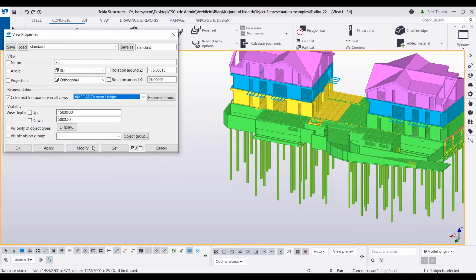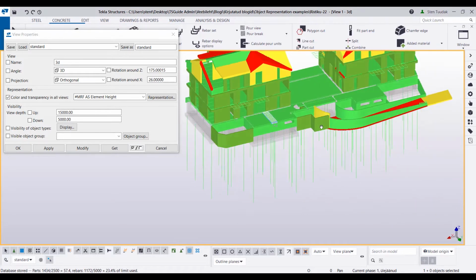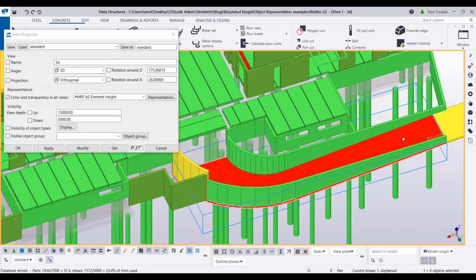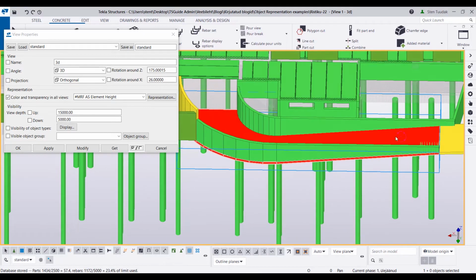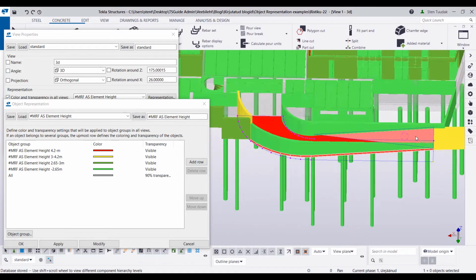The next one that we want to check is element height, and these size limitations come especially with transportation limitations, and that's why it's only assembly level and only elements that are cast in place. For example, these we want to exclude, that it's not important. And here the heights, for example, we can see that okay, this ramp height is a little bit too long, but most probably, yes, what are the limits? We want to avoid height over 4.2 meters, and this element is longer.